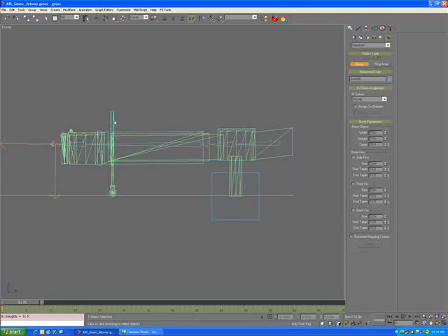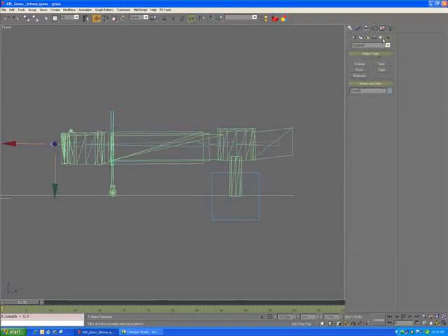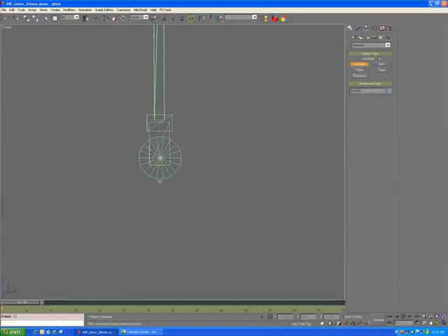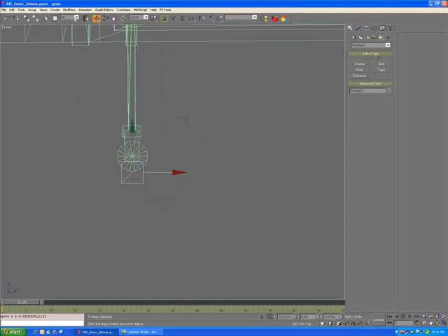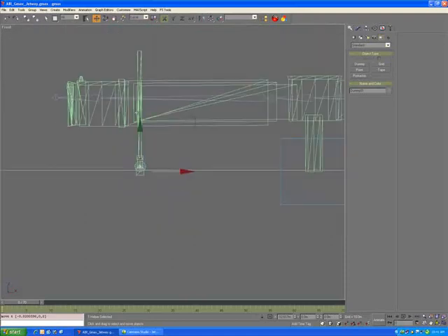And now I want to create one for the legs of the Jetway. Actually, before I do that, I'm going to create a dummy down here, turn off the snap toggle, and just create a dummy down here at the base of the Jetway. And I'm going to set its position to be 0, and this will be used to create the IK handle that locks the wheels to the ground.